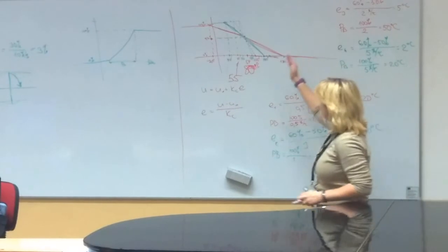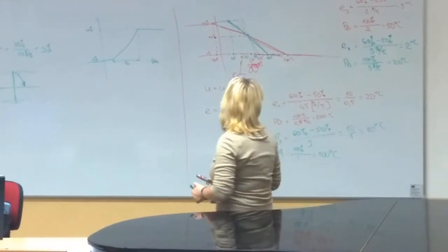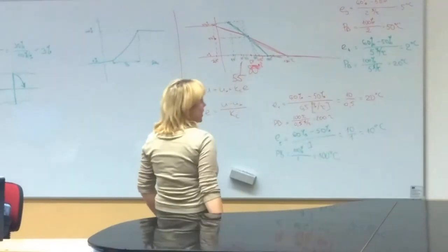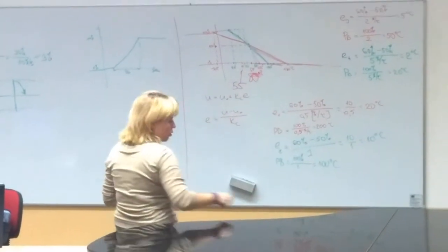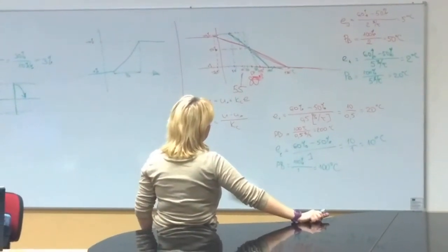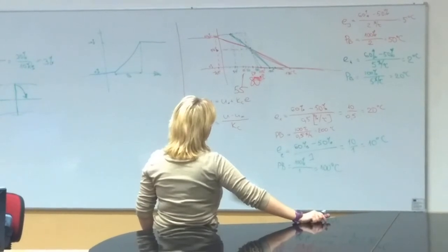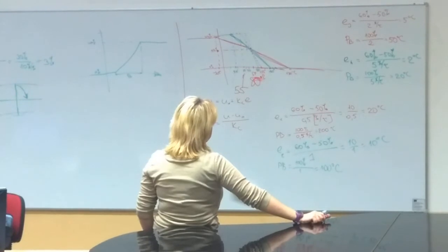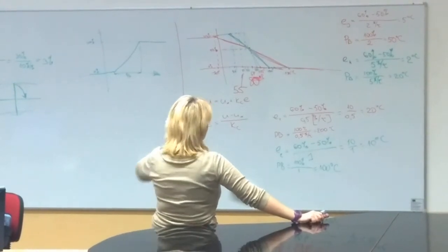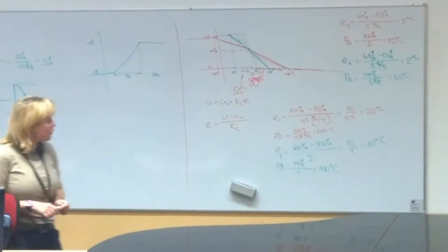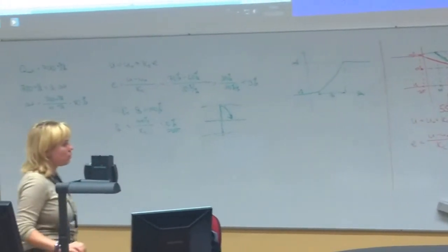So, as you can see, the smaller the proportional band, the smaller the offset error. But on the other hand, in that case we will change our control signal very fast, and we can have oscillations during the control.